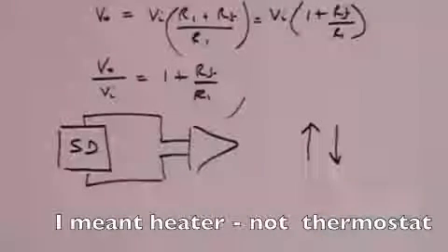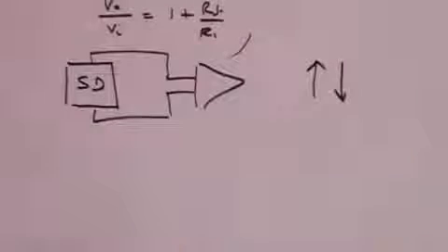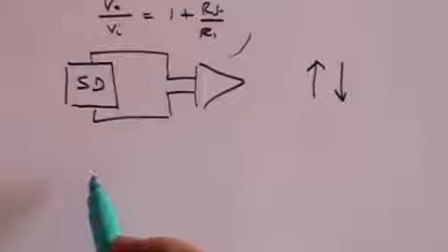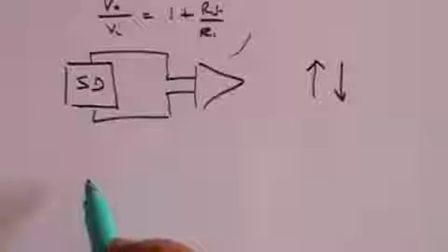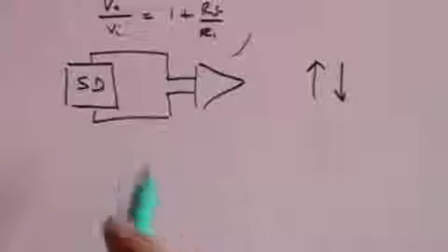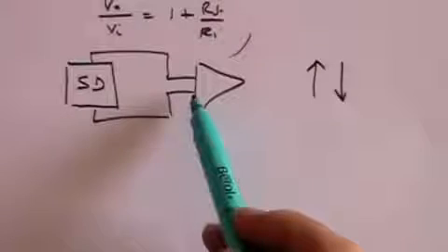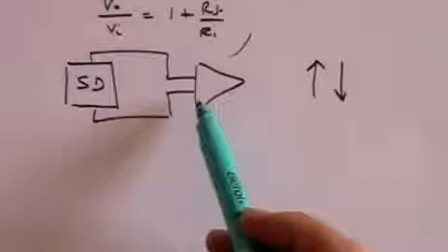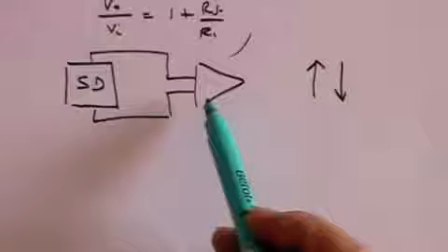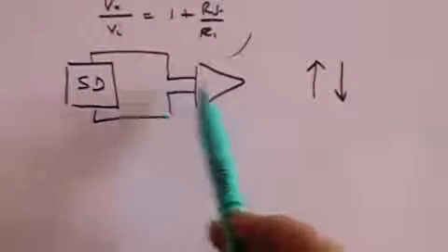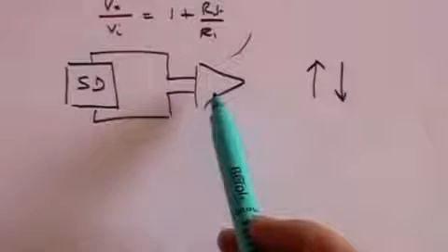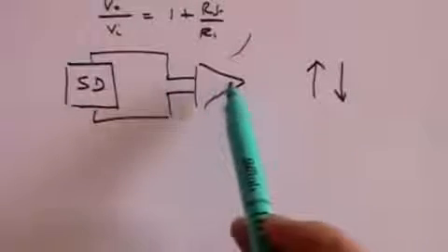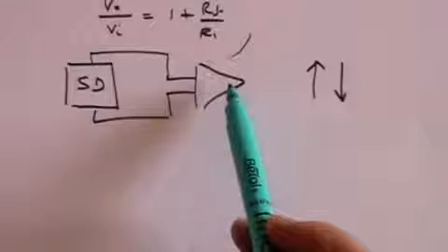And that therefore brings us to the next bit of the debate, which is how then do you get things switched on? How do you switch on the light? How do you switch on the thermostat? And the answer is that you do not want this circuit to be part of a circuit that might be having a very large current. For example, supposing you want to turn on an immersion heater, which might have a current of several amps going through it. You do not want this circuit to be part of that circuit, because then you'll have the potential for a very high current to go through the operational amplifier, and that will destroy it.